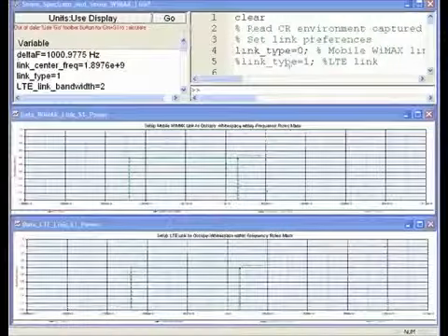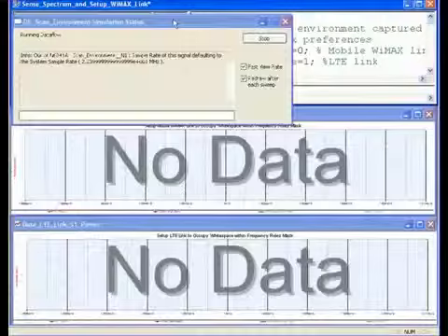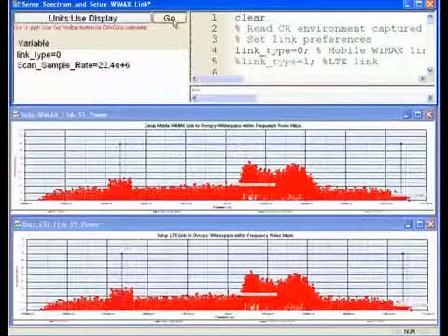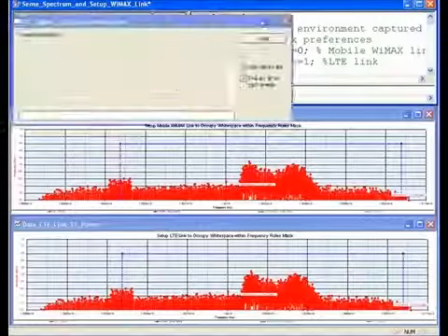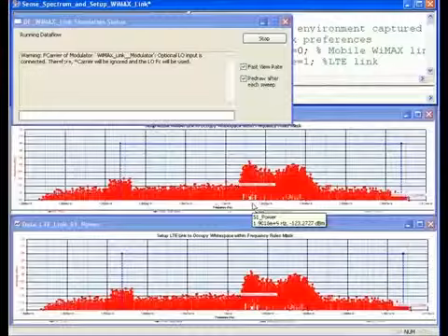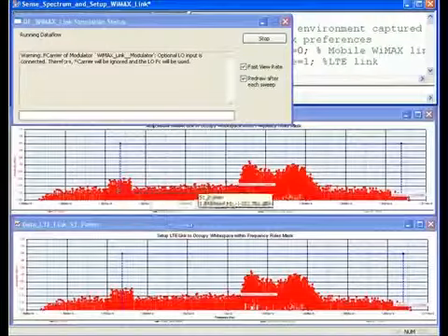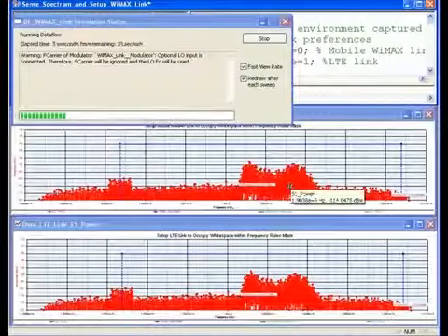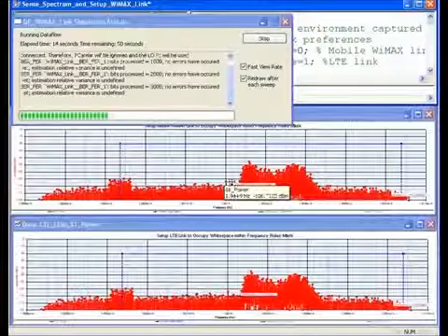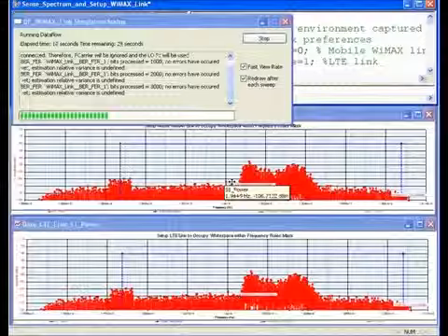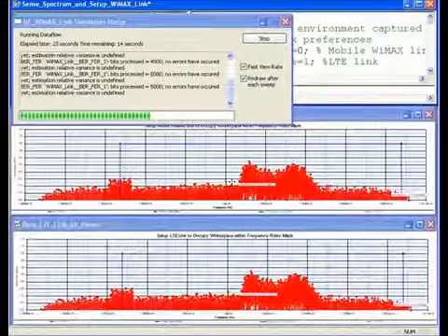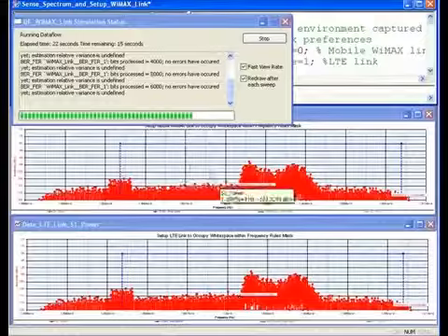To begin the demo, we'll hit the Go button. This will launch the first simulation, which is a schematic that contains the custom RF sensor link element in SystemVue. We can see that the simulation is completed. We've read the remote RF sensor data into SystemVue, and we can see that the cognitive radio spectral environment consists of two spectral peaks. Now the white space algorithm is running in SystemVue to compute the available white space between these two spectral peaks. It'll then try to determine if a 5 MHz or a 10 MHz mobile WiMAX link will fit, and if so, it'll center it between the two peaks.